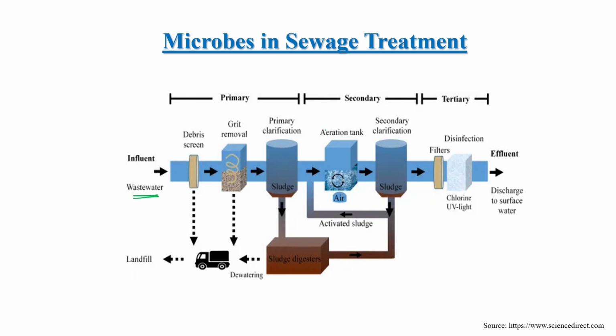In this secondary treatment plant, as you can see, the first chamber is known as the aeration tank. In this particular chamber, continuous input of air is going on. After aeration, the bacteria get activated and continuously degrade or utilize the organic components present in this effluent, right?